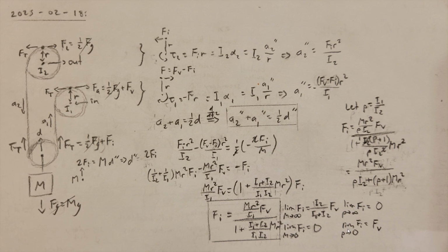Likewise, if the output's moment of inertia is much greater than the input, then it will come to see the entirety of the input fluctuations. The Huygens Drive is simply not a very good way to filter an input, and it is arguably being misapplied.